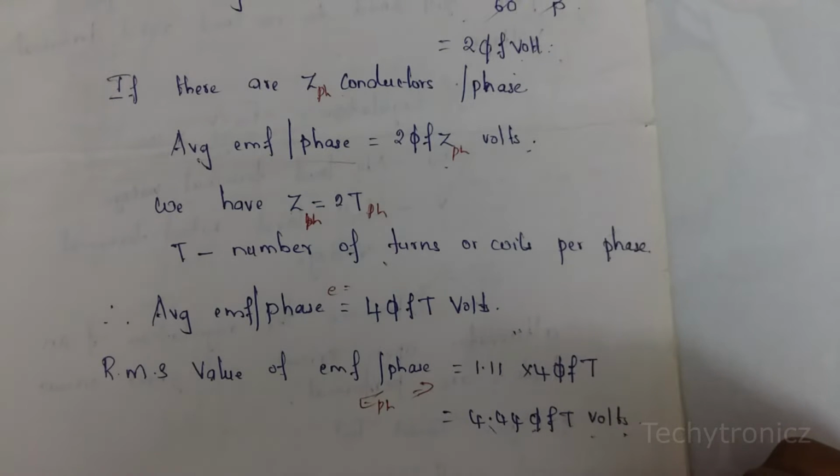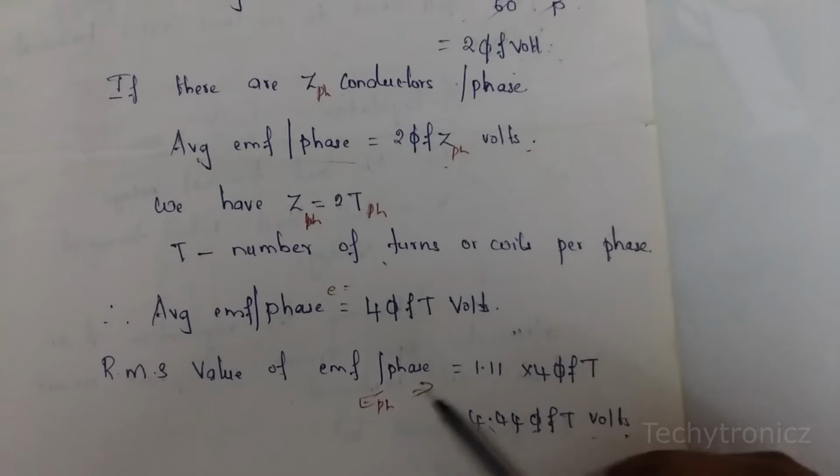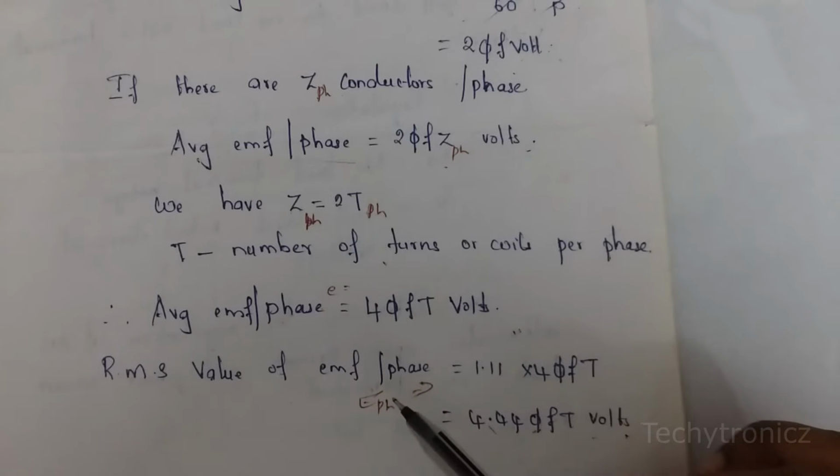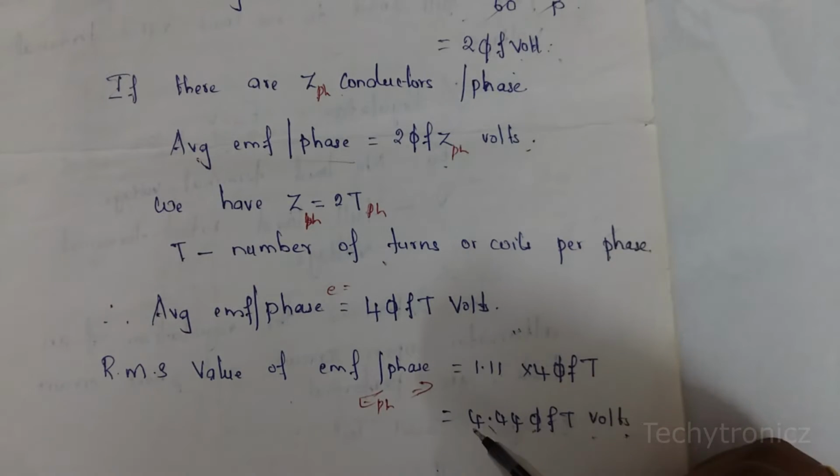That's all about the alternator. An alternator produces three-phase power from mechanical power, and it works on the principle of electromagnetic induction. As usual you have a stator and rotor. In the stator is the armature winding, and in the rotor is the field winding. The field magnets are magnetized by supply through slip rings, and the field windings are connected with alternate N and S poles.